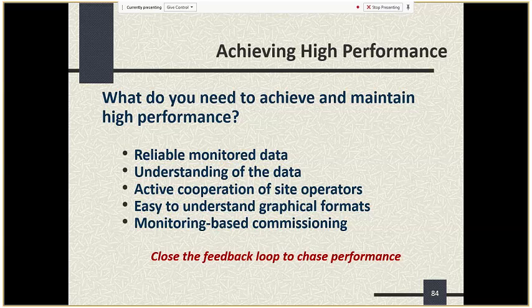You want to operate the facilities according to the original design intent in order to achieve the savings. This is aided by having easy to understand graphic formats and doing a certain amount of monitoring-based commissioning of the systems, especially large energy-consuming systems like the chiller system. And maybe talk a little bit more about that later.